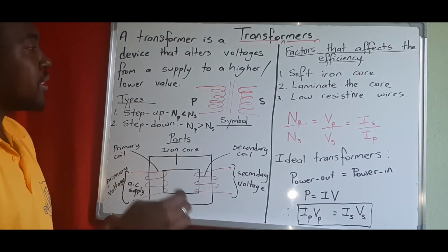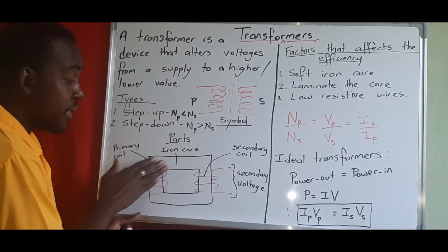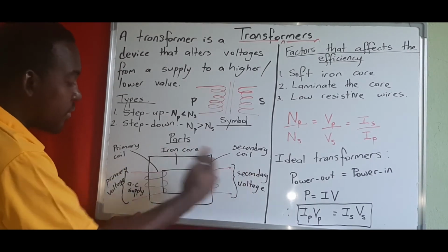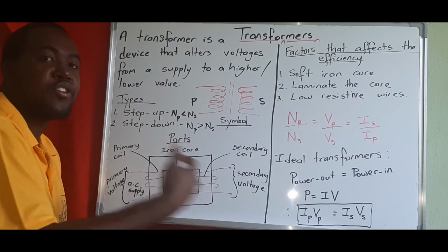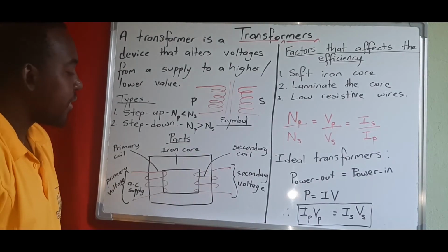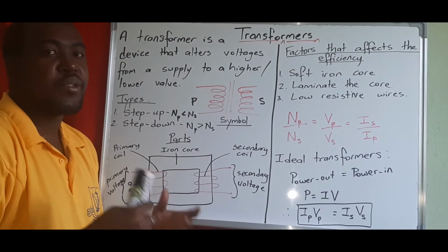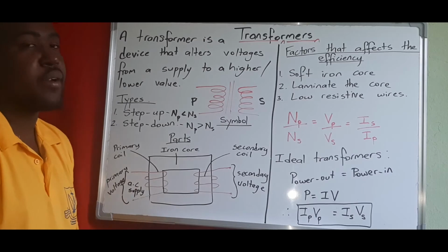So the eddy current is a resistive current that, if the current is going in this direction, your resistive current is going the opposite direction, trying to slow down the change occurring, right? So in that case, we laminate it, put an insulating sheet around it, so it actually reduces the effect of the eddy current, right?